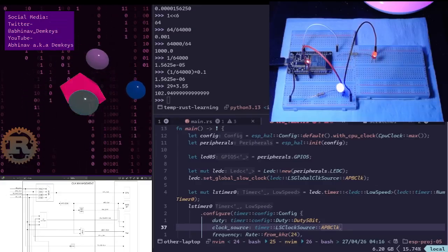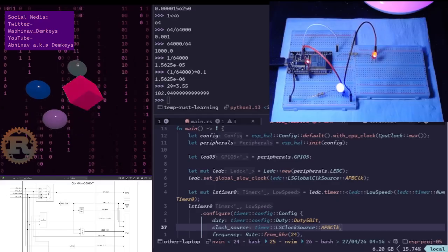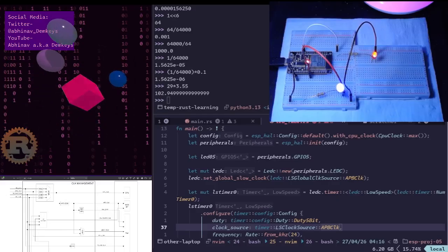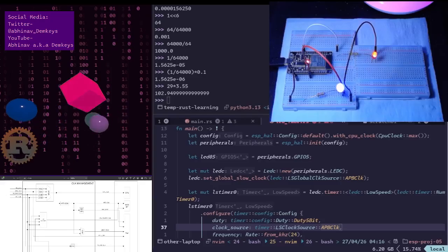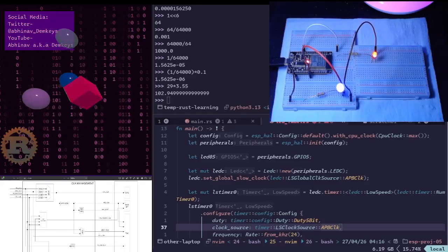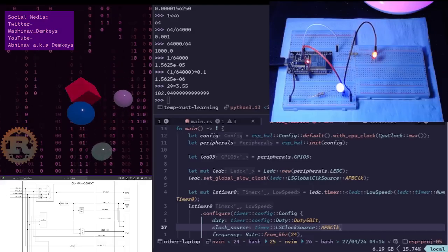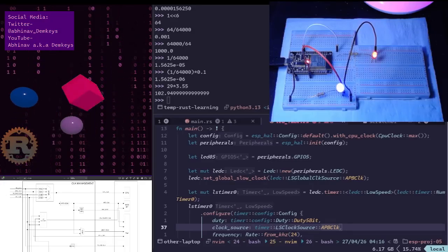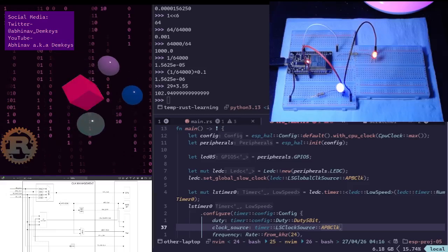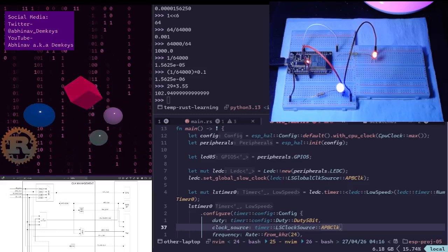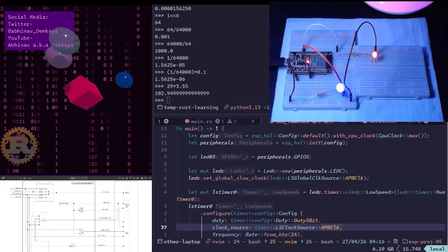The hierarchy of the clock tree. Think of it as a series of valves on a high pressure pipe. You have the source, which is the PLL. This is the high pressure main line, which is 320 megahertz or 480 megahertz. Then you have the CPU divider. This is a valve that taps into the main line and scales it down to say 240 megahertz. This signal is then routed to the CPU core.